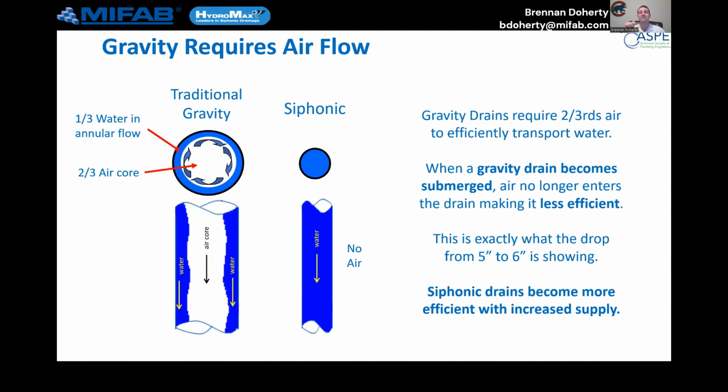We can go ahead and have fewer vertical leaders all throughout our design. Fewer vertical leaders means less chase space I need. Less vertical means less routing, fewer civil connections. Fewer civil connections, less civil coming to the building, less civil pipe work, less slope, less dirt movement, less carbon impact, less site disturbance. See where I'm going with it.